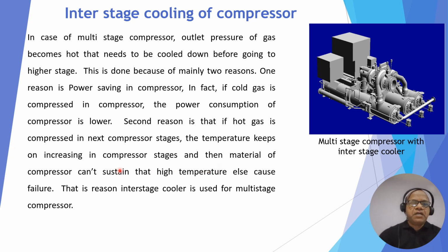The material of the compressor cannot sustain that high temperature, otherwise it can fail, and that is the reason interstage cooling is required. So one reason is power saving, another reason is the limitation of material to withstand high temperature. Because of this, interstage cooling of a compressor is required.